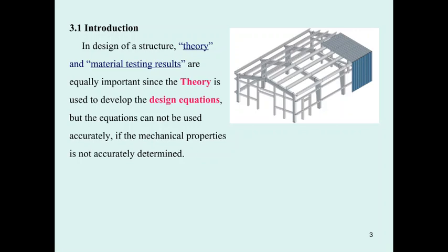to get the data to check that the quality of your material is greater than what is set in the standard. For example, if you test 100 specimens and you get a yielding stress of 300 megapascal, are you going to tell the buyer your material has 300 megapascal yielding stress? If you do, that means half of your specimens pass the mean of 300 megapascal, and half will fail. So the reliability of using the mean is not that high.